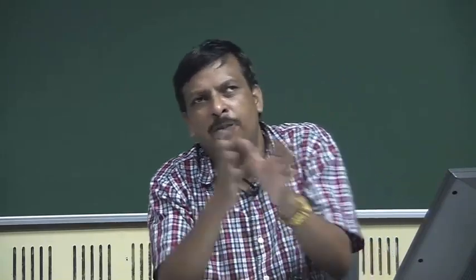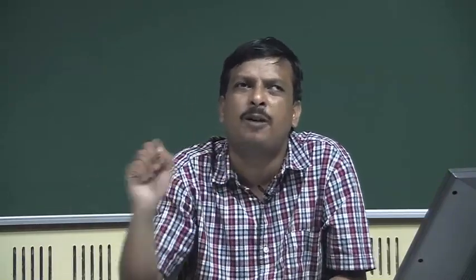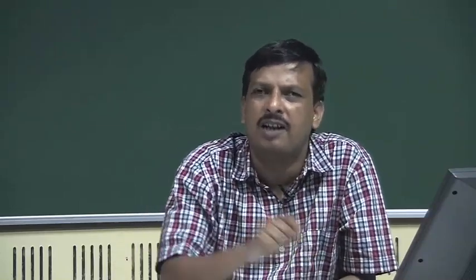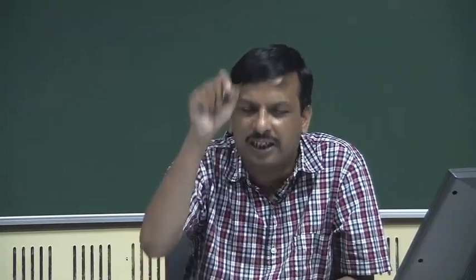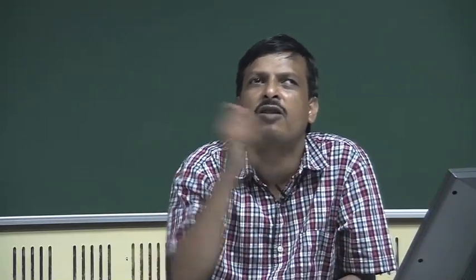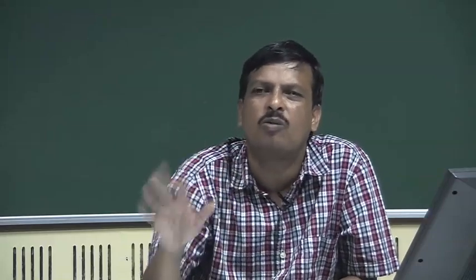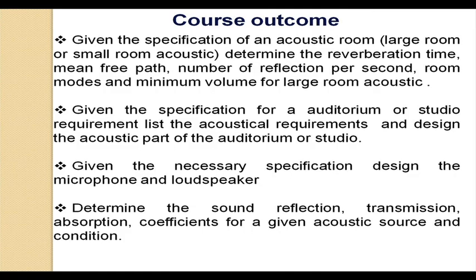Either I give you the specification and you design, or I provide you a microphone and the data sheet, you should interpret each and every point, and you can measure that yes, sensitivity of microphone is claimed minus 50 dB. Yes, this microphone is minus 50 dB, I can measure it by creating this kind of experiment. So, that kind of expertise I want from you when I teach the specification design of microphone and loudspeaker.